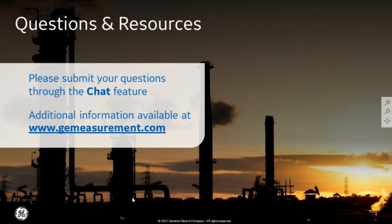For velocity, wedge delay, and sensitivity calibration, can we perform using radius, depth, and thickness similar to OmniScan? Yes, the radius and depth options are there, and depending on the application, whether you're doing straight shots as opposed to an angle beam sector scan, there's where we would use the thickness. So yes, those capabilities are in the instrument.